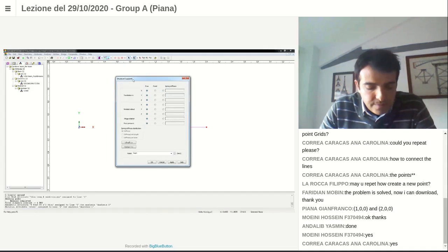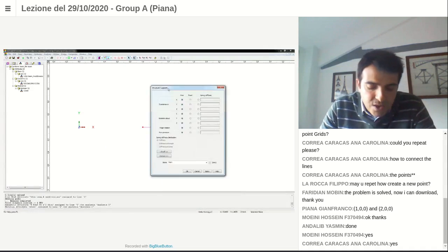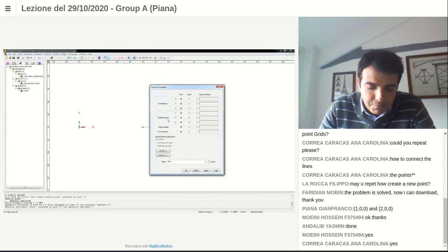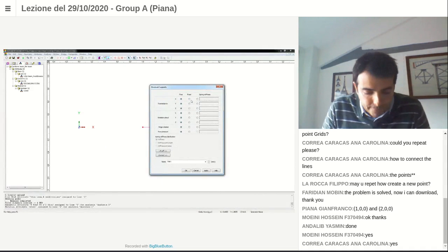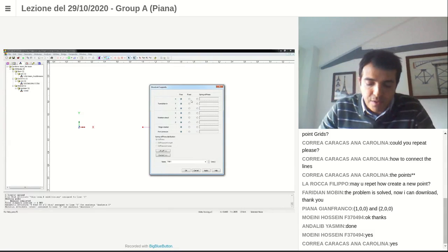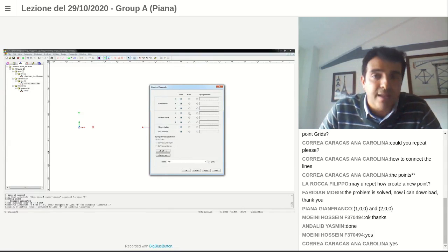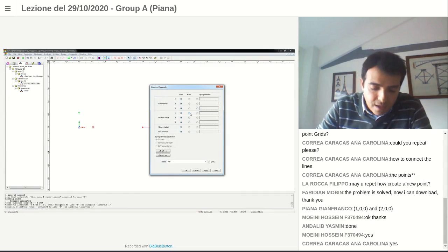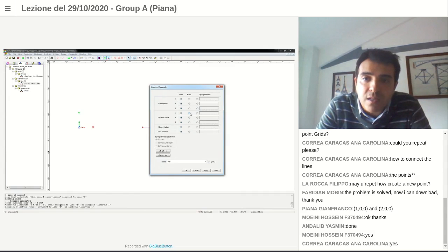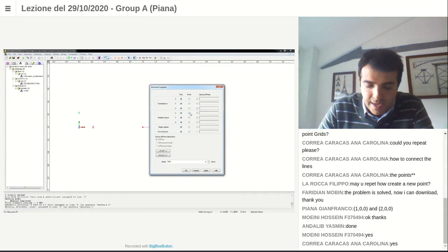And okay, here, in general, for a clamp, a fixed support, you can fix all the degrees of freedom and simply assign that constraint to the left node. But we are dealing with a 2D, a plane problem in the XY plane, capital X, capital Y plane, okay?